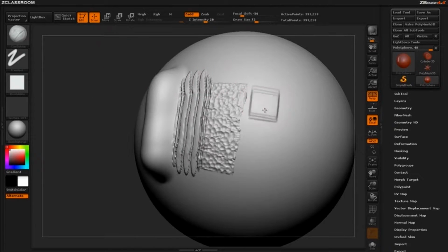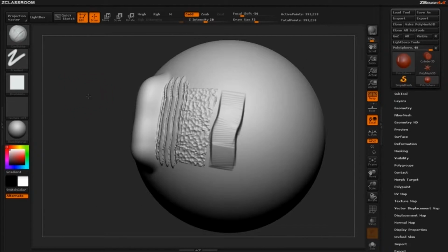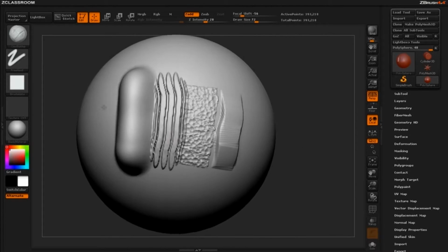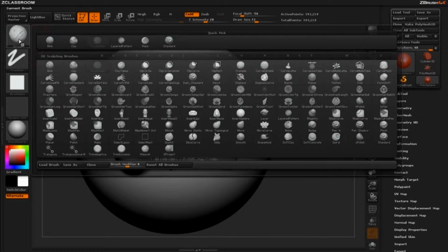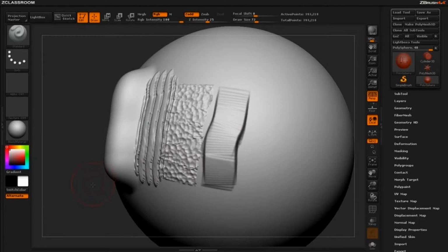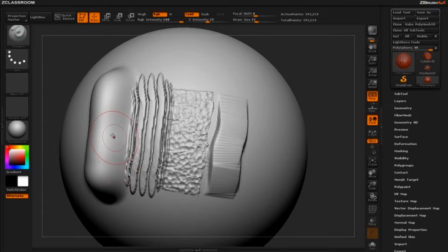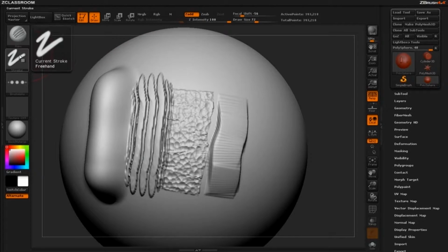If you're new to ZBrush, it's important to note that the brush types will play a significant role in the stylistic appearance of your movements on the surface of your sculpt. Knowing this is important and will no doubt lend itself well as you progress in your sculpting adventures. What is visually represented on your model is derived from the stroke and alpha types linked to the specific brushes you are using. This means that a great deal of what you are seeing visually is the result of the various stroke and alpha settings embedded in the characteristics of your brush.